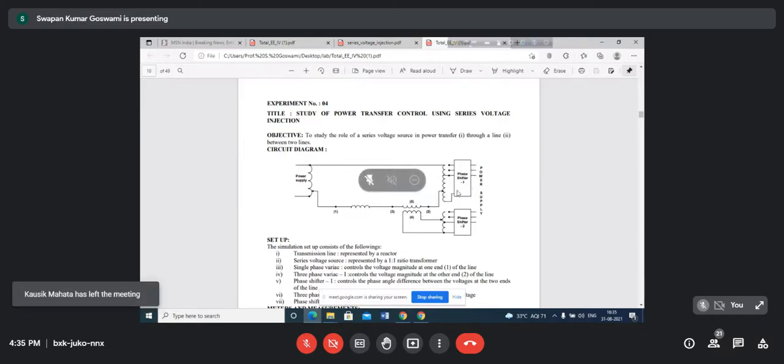So on this side you have a three-phase variac along with a phase shifter. The three-phase variac will be there to control the voltage. Here the single phase variac is there because we are actually dealing with only one phase. Only one phase will be considered here, but a three-phase variac is required at this end because we shall be using a phase shifter at this end.